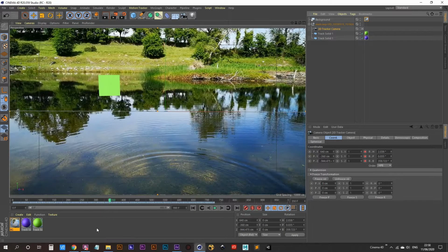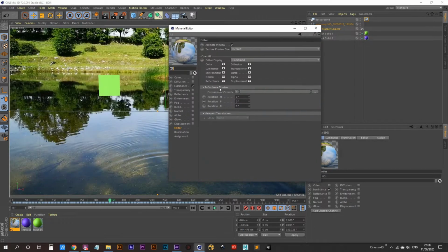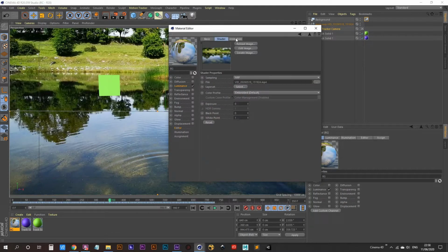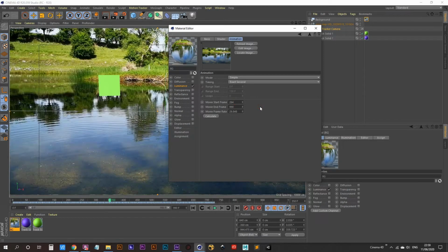So if we jump back into Cinema 4D, let's open up the background material, go to our luminance channel where our video is, and then click on this thumbnail. Now go into the animation tab, and we need to tell this to start at 264. Start frame 264. And we also need to make sure that the frame rate is set to 30.